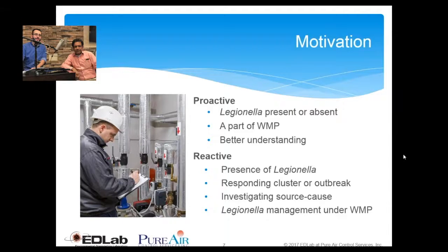And obviously, if you have Legionella, then you should have a Legionella management program under your WMP. WMP is going to be used in this presentation throughout. That stands for Water Management Program, and that is a better way of responding in case of a reactive mode. Those are the two motivations I can see for people taking on this important task.